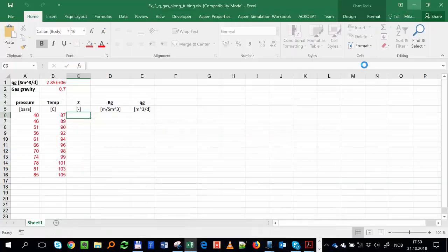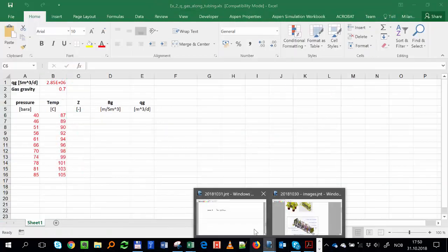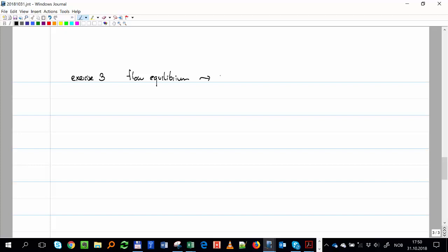What you have to deliver in that exercise is first the bottom hole equilibrium, and that means IPR. Remember, IPR stands for inflow performance relationship. If I wake you up in the middle of the night and ask you what is IPR, you have to tell me inflow performance relationship. Or if you don't know the name, you say it is the available pressure at the bottom of the well calculated from the reservoir. I will prefer that answer.